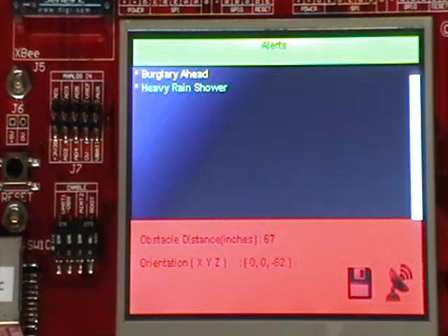And then you see a floppy sign that says the SD media has been inserted into this device. Why would I be using the SD card? It's to store the alert values. The beacons would push this environment information to this mobile unit at different times, and these values might not change that frequently, so you can hold that data on an SD card.